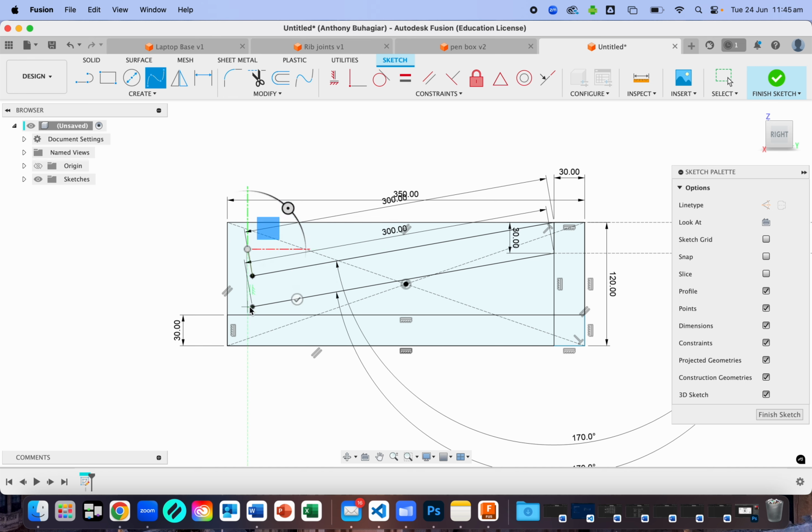So the way that it works is that you click on where you want the spline to start, you click on where you want the spline to end, and then you obviously have a piece in the middle as well that you have to place, and you can play around with adjusting that spline once it's been drawn by dragging on those curves that you've drawn.